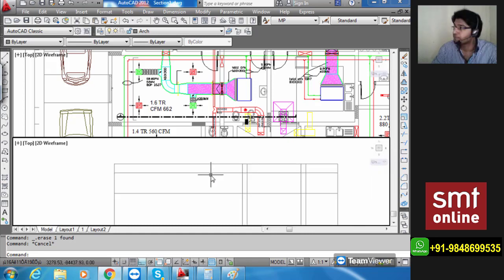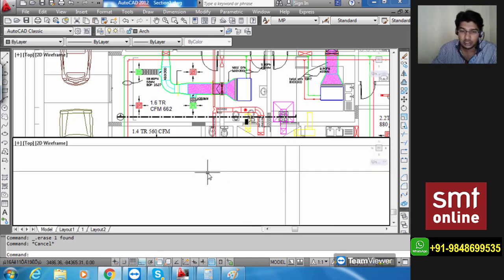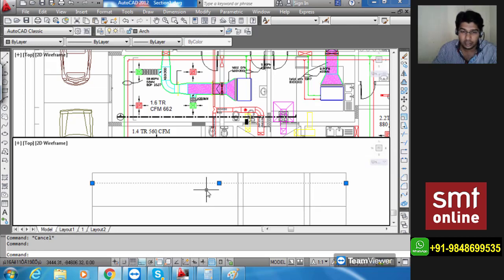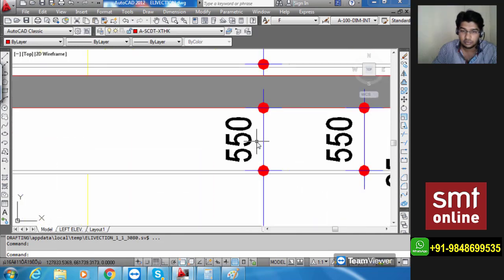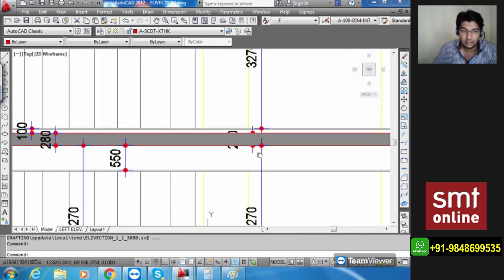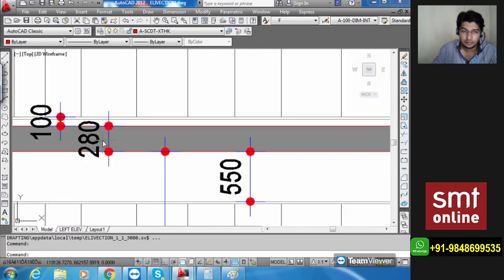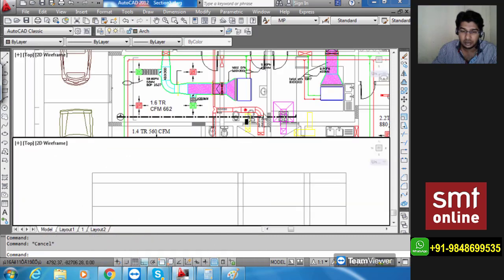Now I'm having little space, so over there I can apply the 300 mm of structure slab and also the 100 mm of my void space. So from here, how much do I need? Again, from the FFL, you can come to the drawing and see what we have next. After 550 is what I have my 280, right? So 280 plus 100 is totally 380. So we can take directly 400 instead of keeping 380, the odd number.